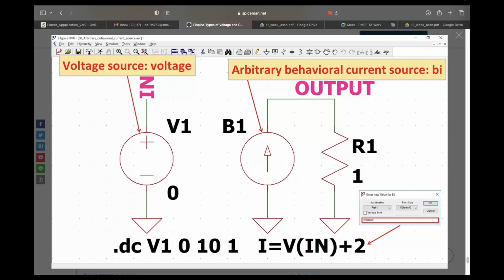Sir, according to the values, it will get V0. How, sir, while we are plotting, how to get V01, V02? While plotting, you won't get V01, V02. You will just plot the output waveform, and you take the FFT of the output waveform.